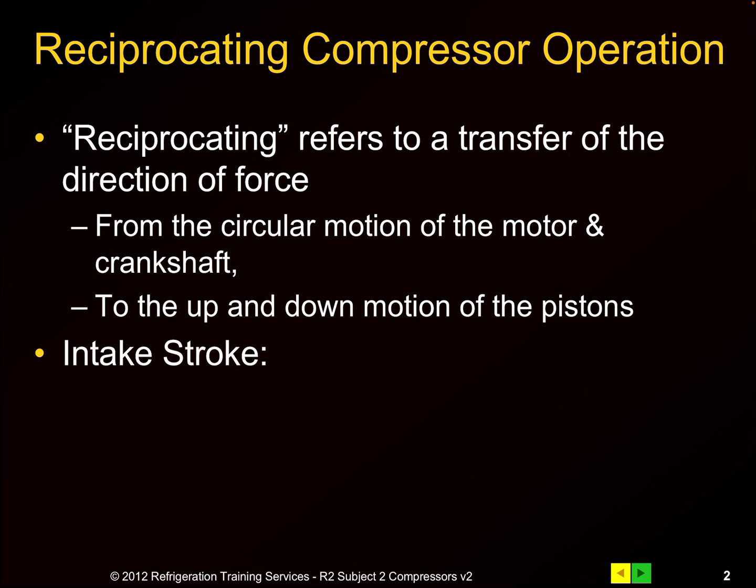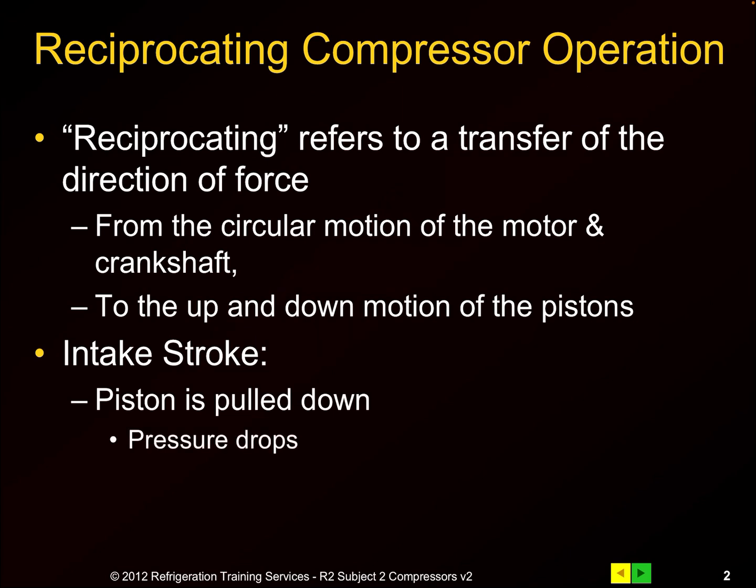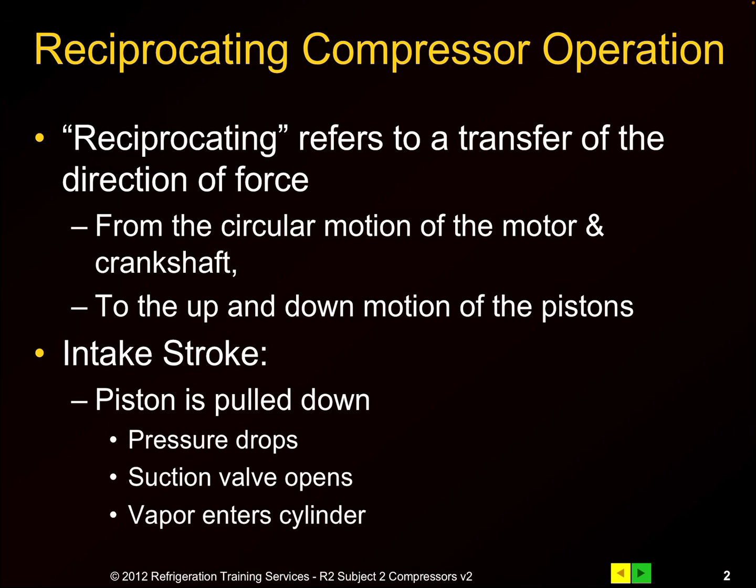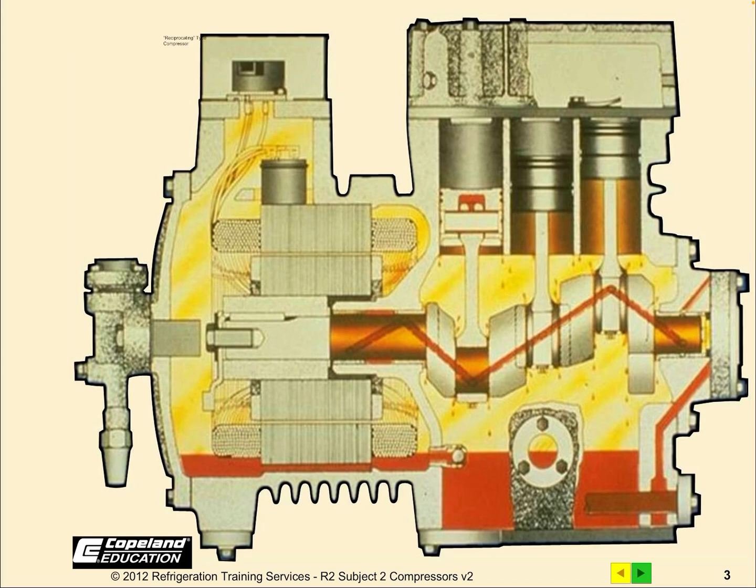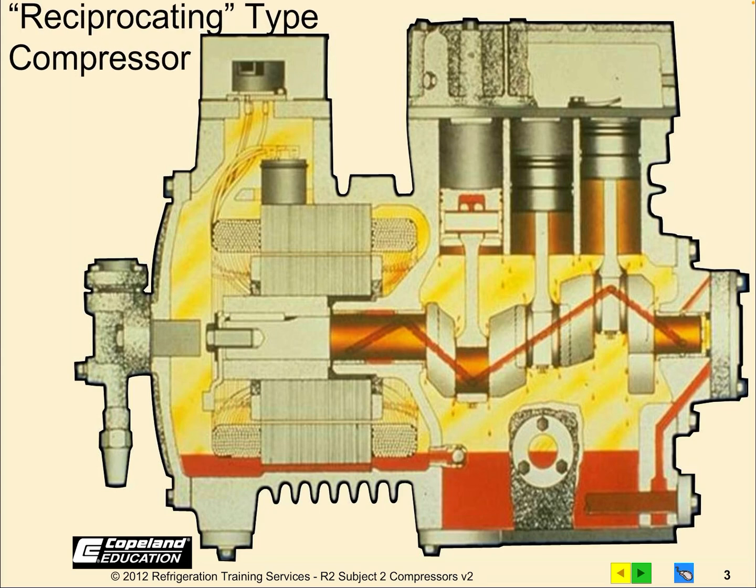There are some key parts of the reciprocating operation. The first is the intake stroke, where we pull the piston down and lower the pressure. We open up a suction valve and allow refrigerant vapor to enter the cylinders. So that's the first thing that happens.